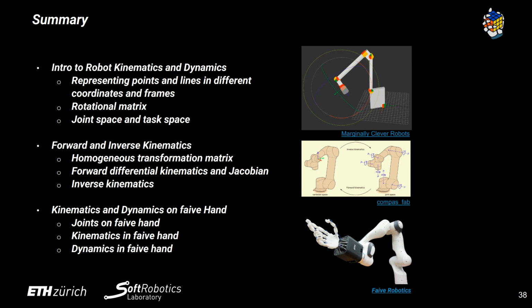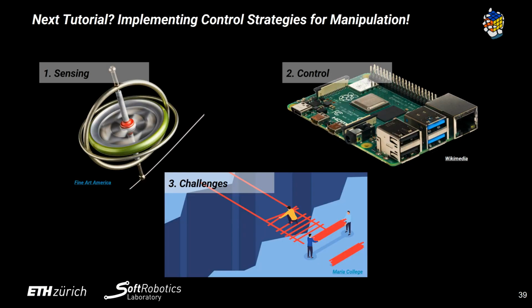With this specific case study of the rolling contact joints on the 5-hand, we ended up analyzing and developing the kinematic equations based on its physical structure. We also then modeled the dynamics equations of the 5-hand. This is also vital to know, as for a robotic hand, you want to manipulate an object, and the forces are just as important as the position and orientation of the hand. Now we know how to get the kinematics and the dynamics equations for a robotic hand with rolling contact joints.